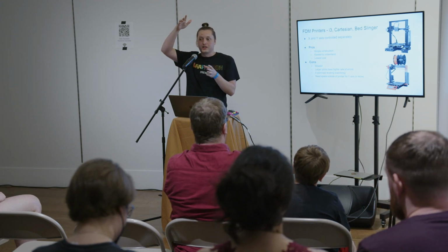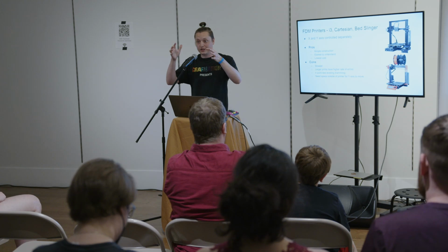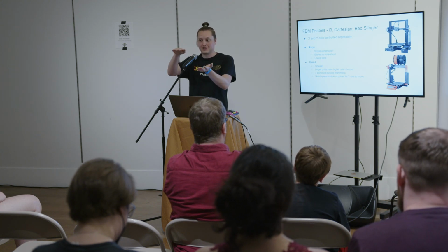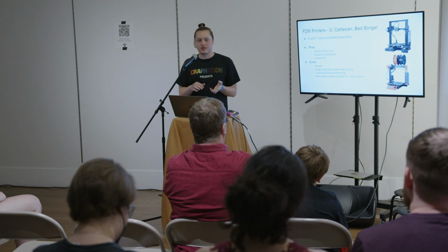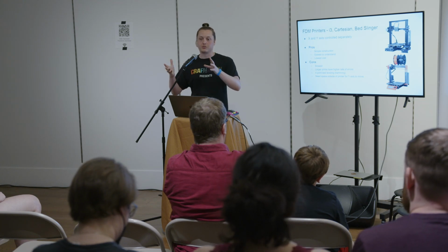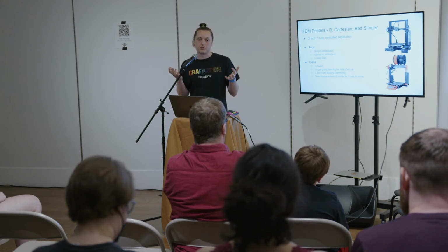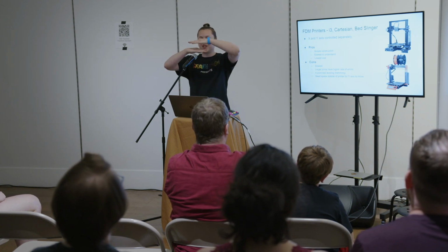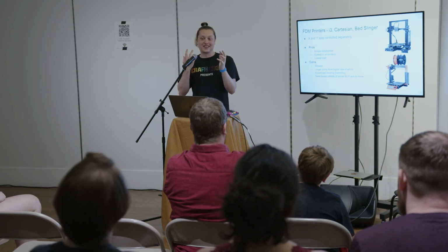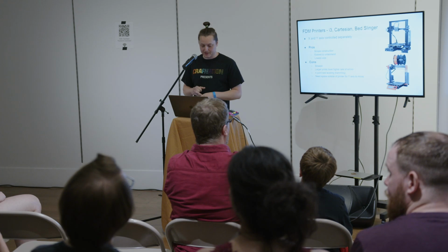For cons, due to the fact that it has to move the entire build surface, it means that the larger your print, the more volume and mass you're adding and having to move back and forth throughout the entire print. So it becomes heavier and harder to move. There's a lot more weight, so it has to print slower so that you don't have the print shift midway as weird things happen with the stepper motors.